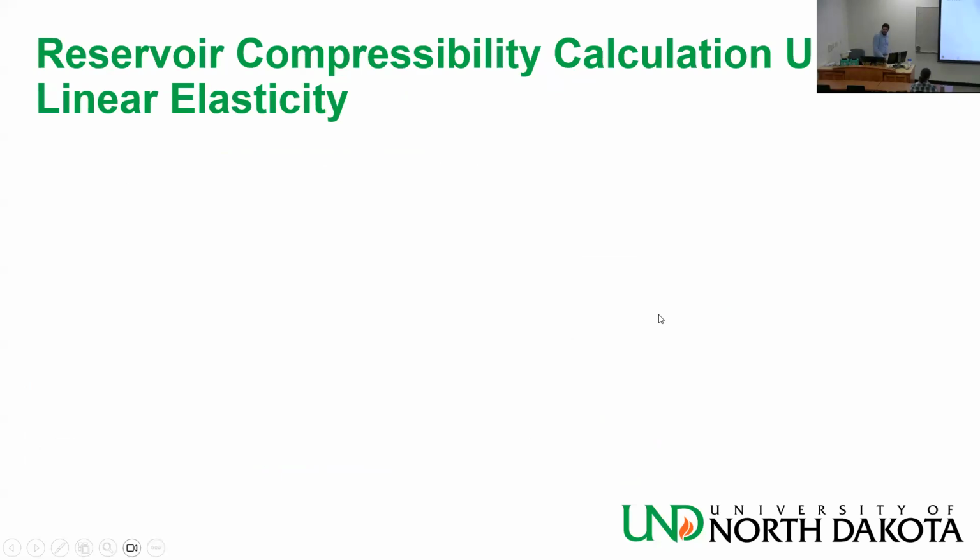Reservoir compressibility calculation under linear elasticity. Remember, in the exam, you don't need to memorize any equations like the matrices and stuff. Those I'm going to give to you. But things like how you get from bulk modulus to compressibility, I'm not going to tell you because you need to know that you reverse bulk modulus, you get compressibility.